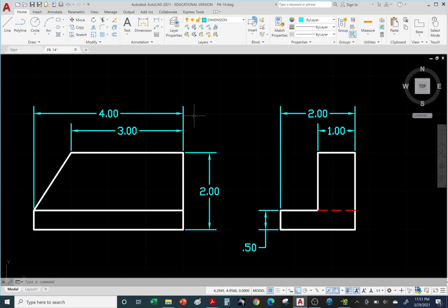So when dealing with holes where you want a tight fit diameter and control it, then you will go to 3 decimal places on the diameter of a hole, and maybe even up to 4 decimal places. But typically 2 decimal places is the way to start, and then you can work your way to 3, maybe 4 decimal places, depending on the function of the circular hole, depending on what type of fastener you're going to put, whether it's a bolt, a dowel pin, etc.